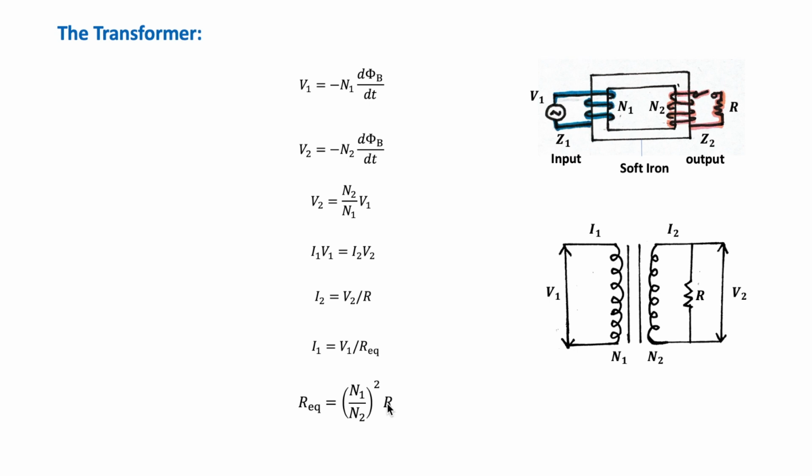So if the generator voltage is stepped up, the current in the transmission lines is reduced, which will reduce the I squared R heat losses, right? Then the voltage is stepped down at the distribution station, and then it is finally stepped down to 120 or 220 volts at the customer's utility poles.